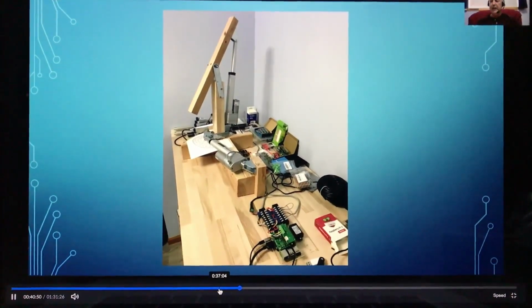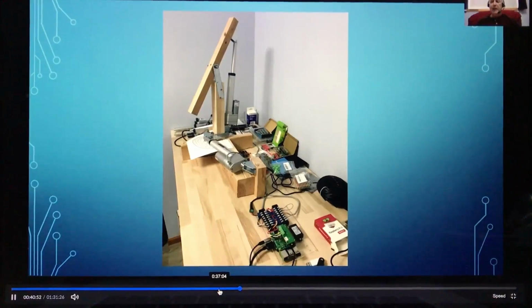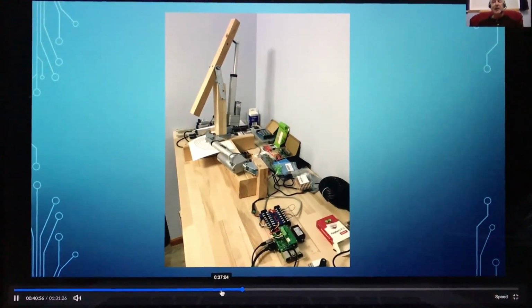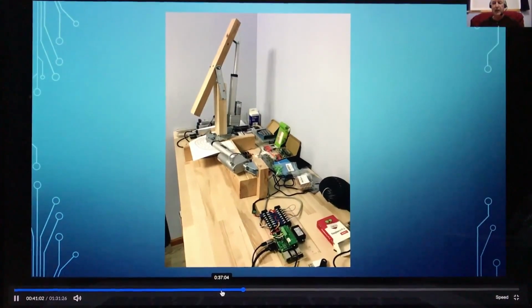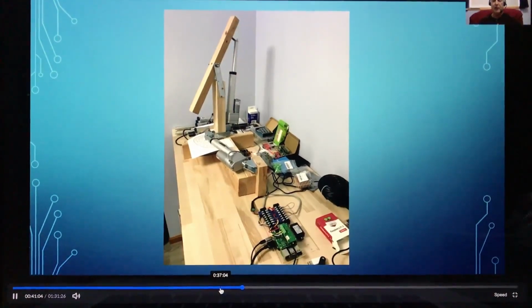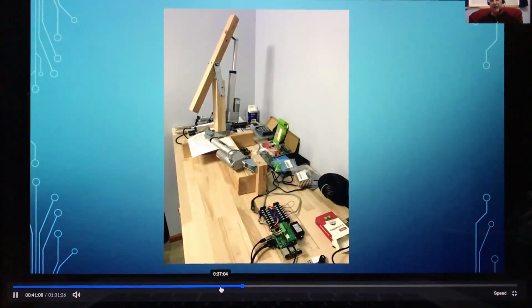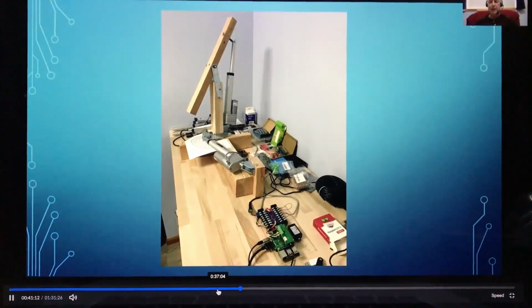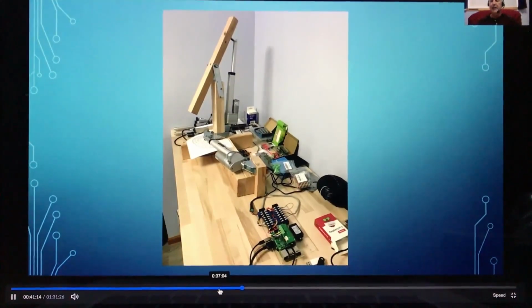Every minute the app compares the PVLib provided solar data to the angles that the system is at. And if that error exceeds a threshold, the appropriate actuator is activated to move the system back into alignment with the sun.